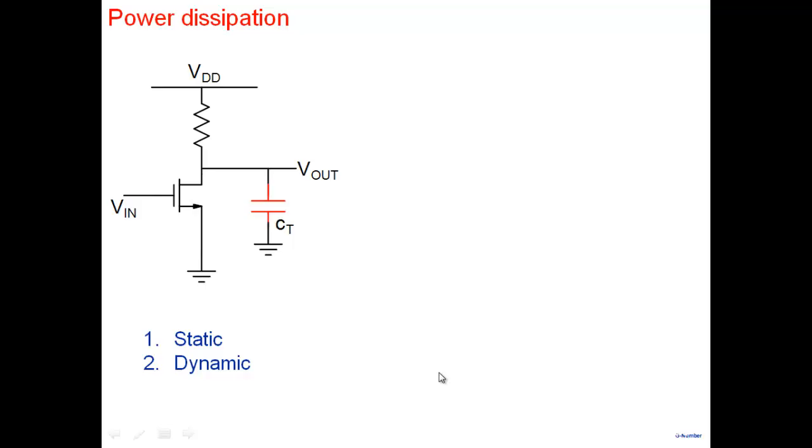Now, how is the heat related to clock frequency? Well, you'll see it in this simple discussion, which will illustrate the relationship between the frequency that I'm talking about and the power dissipation. So there are two kinds of power dissipation. One is what we call static, and the other one is dynamic. Now, let's understand. Static means the following: I've applied, let's say, a 0 here, which is, let's say, ground. And the system, 0 is there, and that's it.